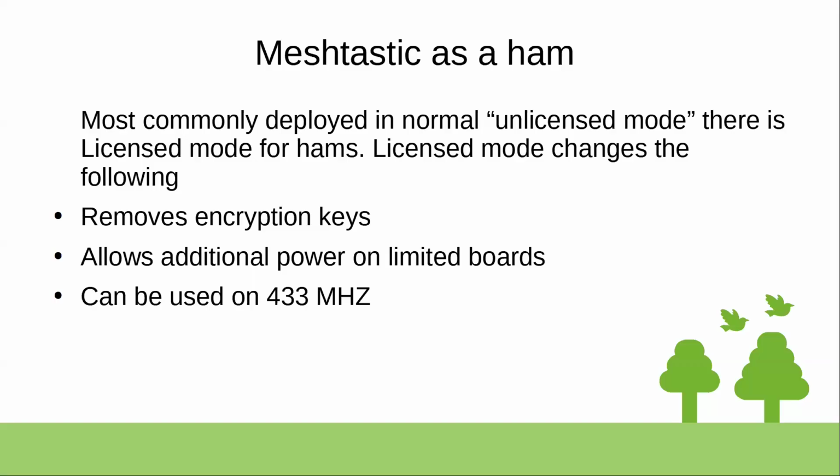You can go out and find the same hardware, but just with a different radio in it. But I don't think that's really common. Also, the 433 is way busier in the spectrum. That's what tire pressure sensors use, and cheap wireless doorbells and all that sort of thing. So the 915 is a bit cleaner and a bit more effective.